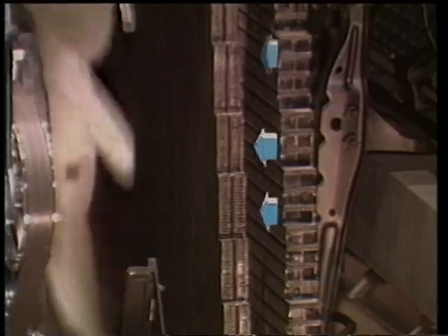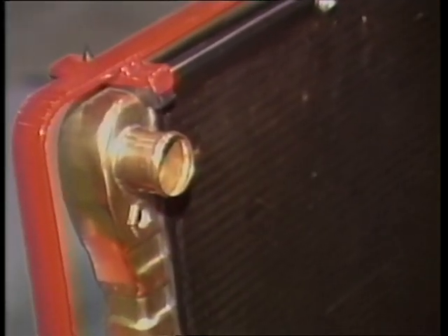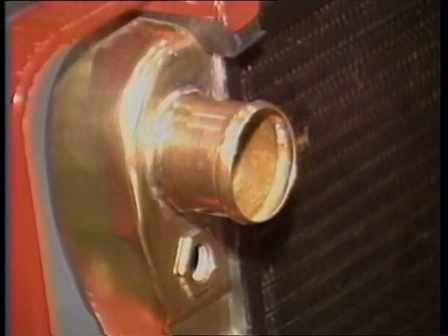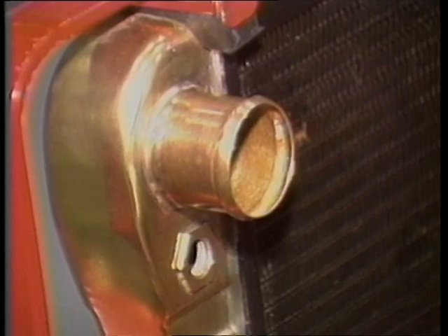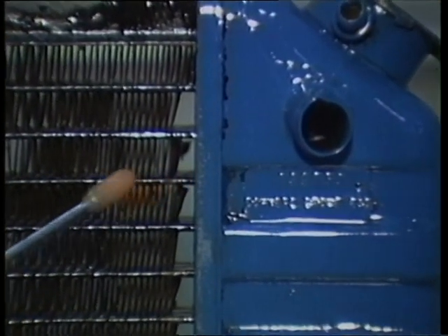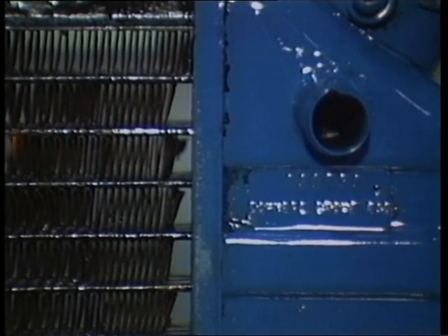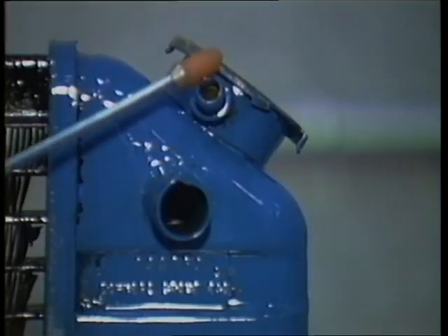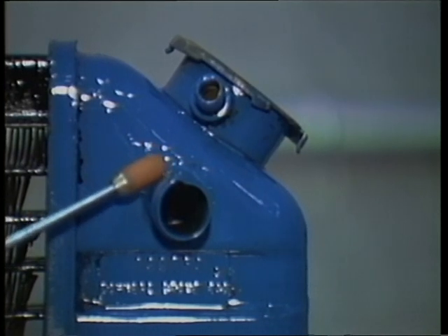The radiator consists of tanks soldered or bonded to a core. Metal tanks are soldered in place. Plastic tanks are bonded. The radiator core has a series of small metal tubes attached to cooling fins. The radiator neck and hose fittings may be formed on the radiator. Sometimes a heater hose fitting may be provided on one of the tanks.